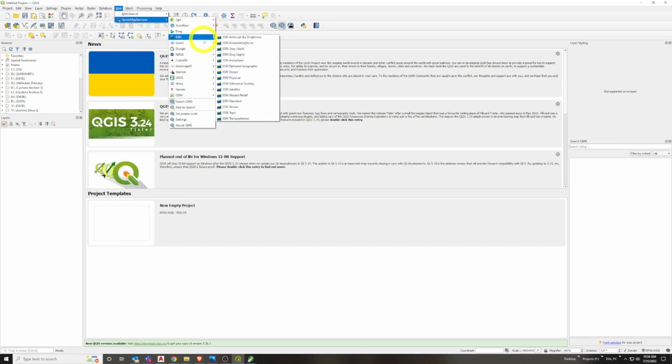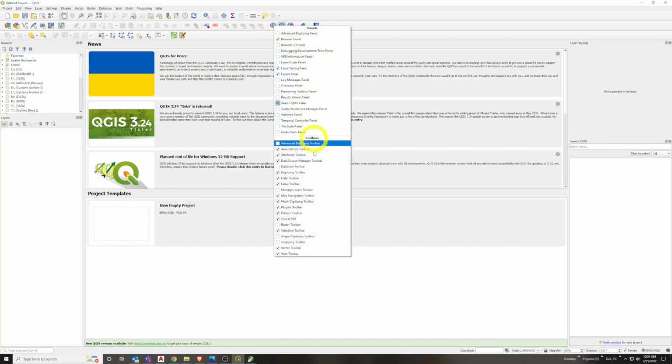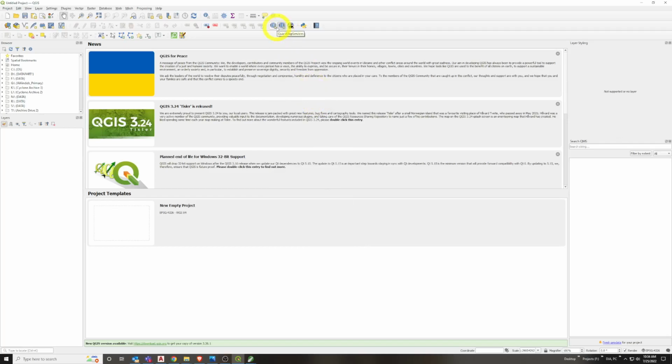This open source software seeks out Esri, Bing Maps, USGS Maps, NASA Maps, Google Maps, which I use quite often. It'll probably bring a toolbar in here as well with the Quick Map Services. It should. You can also populate these toolbars this way by right-clicking. Very typical in a lot of programs to turn on and off. The QMS is the acronym. Turn that on and off. So look for those things after you install to get it running.